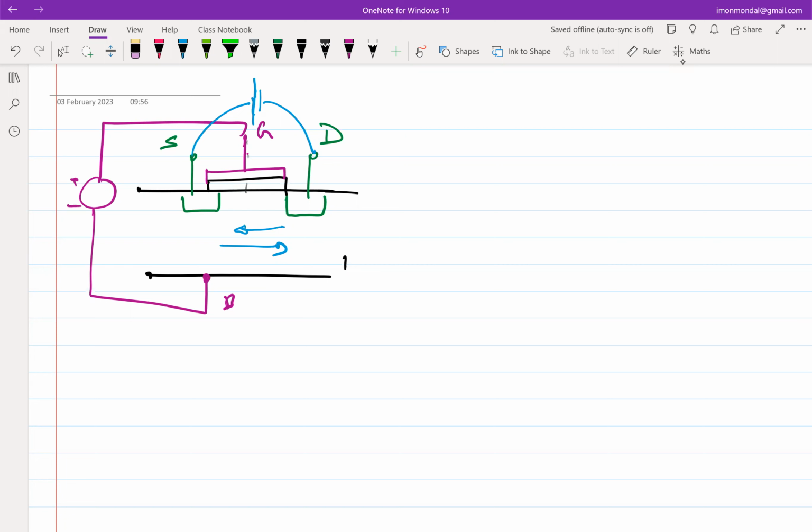Another terminology is the fact that we started off saying that this is a p-type semiconductor, and the charges that are giving rise to carrier transport in this channel are electrons, right? Because we initially applied some voltage between gate and body, and we drove away the holes, and we kept on driving them away till we had mobile electrons. So the carrier transport in this device is being facilitated by electrons, which is essentially N-type. So we call this particular device an NMOSFET, NMOS. Okay, this is an NMOS transistor, or it's called NMOSFET.